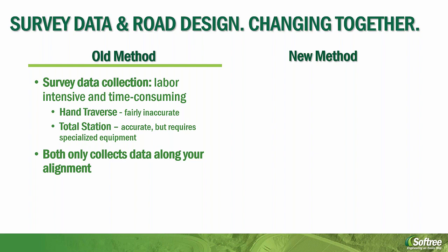So if you want to put the road here, you usually just survey along where you want to put it, and get the topo data to go from. You don't get that landscape level coverage that you get with LiDAR, where you can say, oh, well, let's try it over here and see if that's better. You're stuck either going back out to survey or making it work with what you have.